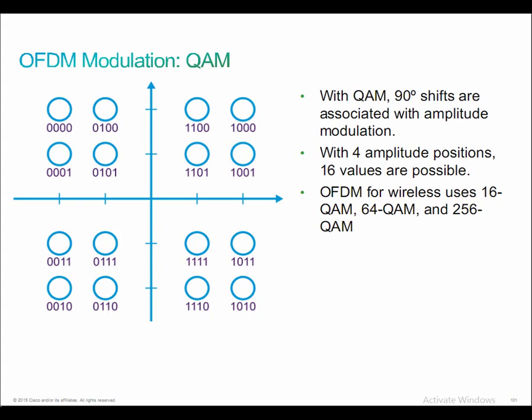The modulated waves get summed up together, and then the final waveform is a combination of both the phase shift keying concepts that we learned in the previous slides and amplitude shift keying, which is what we're going to learn about now. In analog, we use something called phase modulation, but we don't use that in digital transmissions.